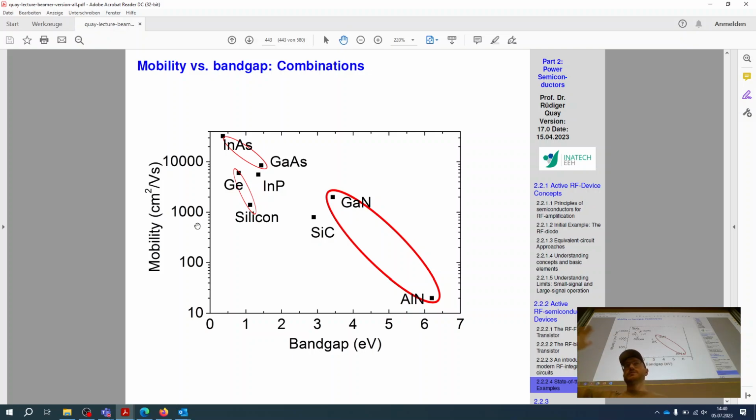From 200 gigahertz to around 400 gigahertz, I would say SiGe is quite advancing, in that you can have integration by combining a SiGe node with a silicon node, so that you can have not just the RF amplification part in one chip, but also other components such as a local oscillator, a VCO, a PLL loop, or whatever you require to form a system inside one chip, and not just have these power bars that parallelize, so you have a complete system.